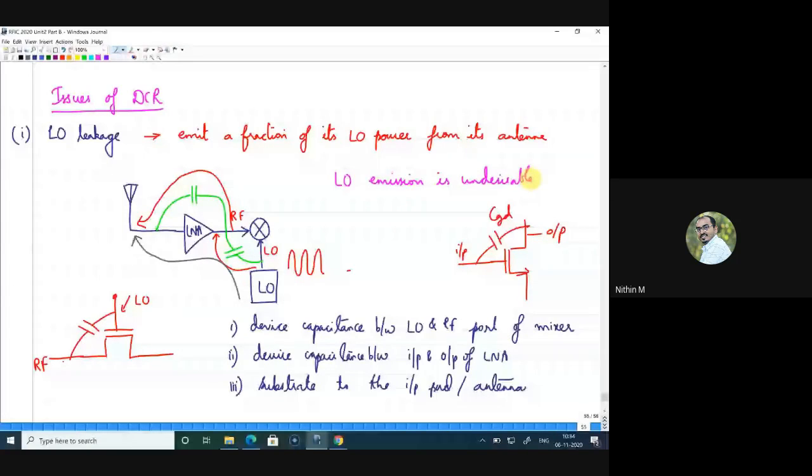Yes, here there is a constraint to match the frequency exactly as omega RF, so the LO leakage becomes significant, whereas in heterodyne there was no particular constraint. Nagaraj, yes, I'll come back to the answer for that. Yeah, the receiver is acting as a transmitter. Yes, Abhinav, it is right.